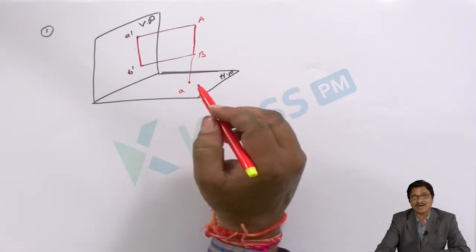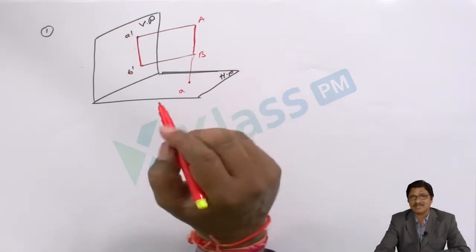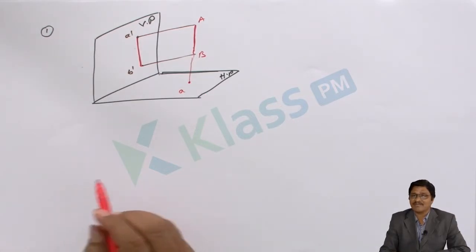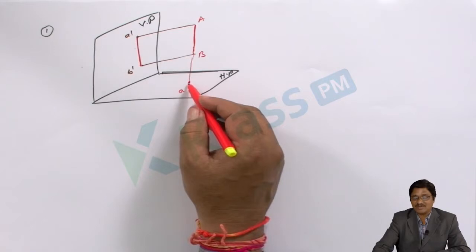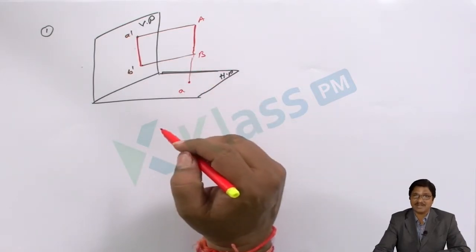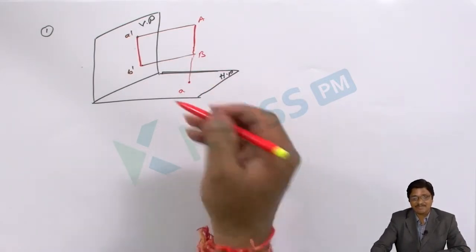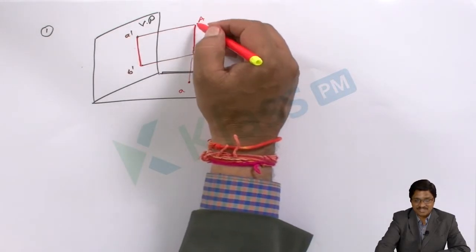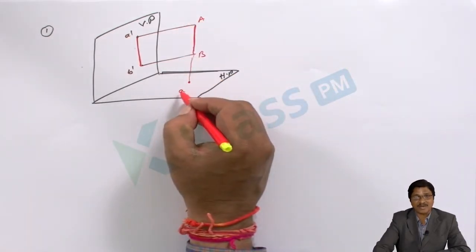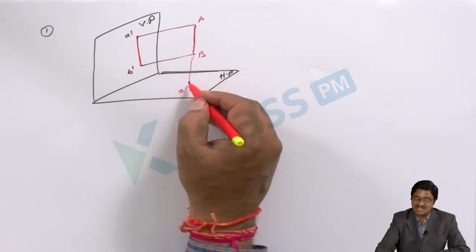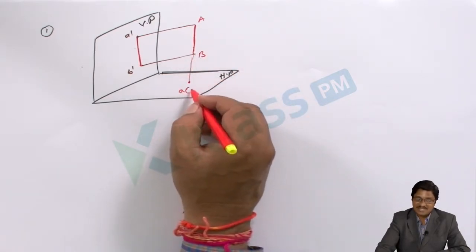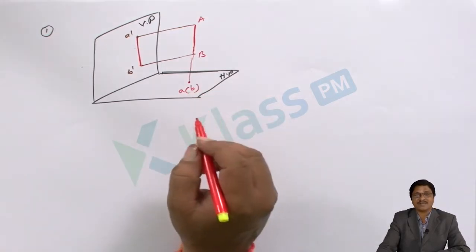Whenever it is a straight line, we have two endpoints, but you are marking only one point, so there may be doubt. The one we view from the top which is visible will be kept open. B is there but it is not visible, merged with the same point. Which is not visible has to be given in brackets.